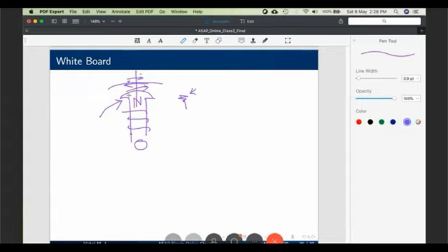So to prevent hunting, there are damper windings kept on all poles. It's like a squirrel cage induction machine. Whenever there is hunting, you have relative motion between stator field and rotor field. So induction action takes place, and working on that difference in slip, it will try to nullify that slip. So remember, your starting damper and hunting damper are both different.